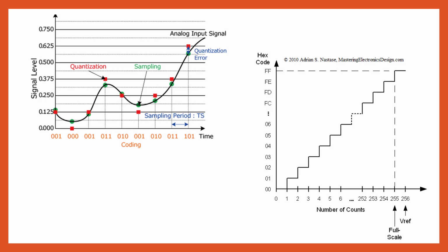If those steps get smaller and smaller, they get closer and closer to a straight line. As we increase the sample rate, what we're effectively doing is making this part of the step, the run, shorter and shorter, because the distance between samples is getting smaller and smaller. That makes this part along the horizontal axis smaller and smaller.